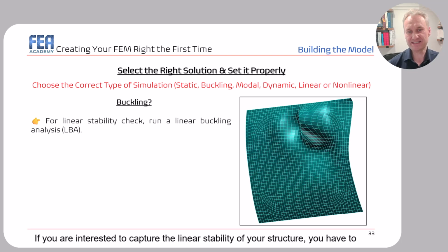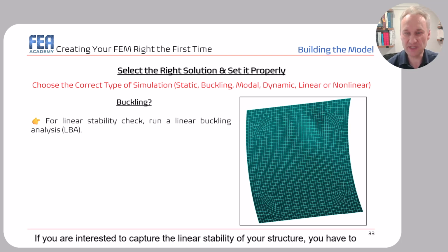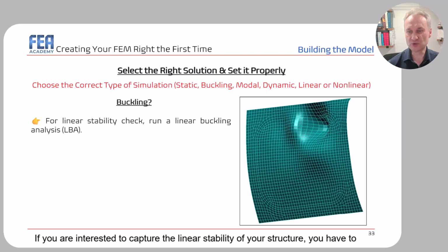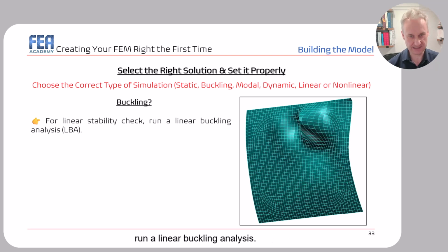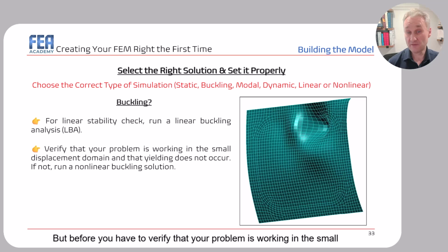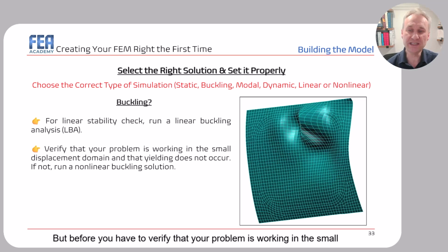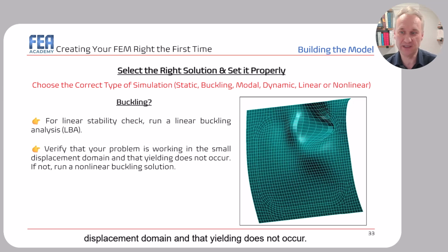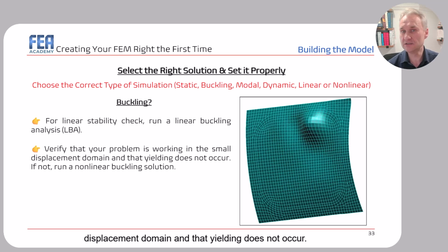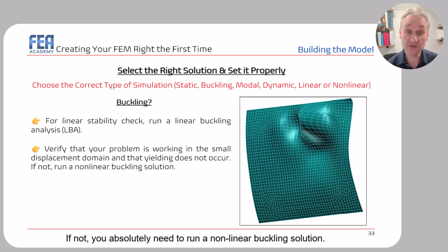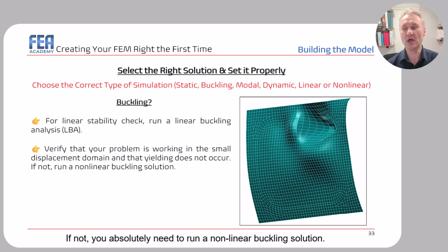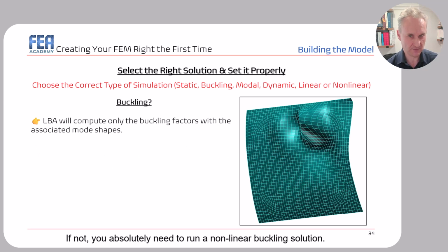If you are interested in capturing the linear stability of your structure, you have to run a linear buckling analysis. But before, you have to verify that your problem is working in the small displacement domain and that yielding does not occur. If not, you absolutely need to run a nonlinear buckling solution.